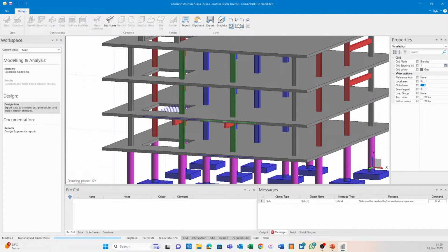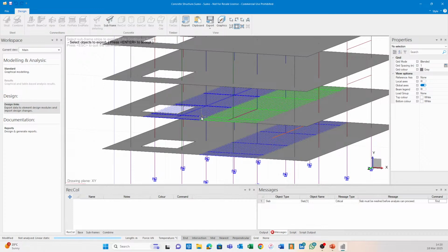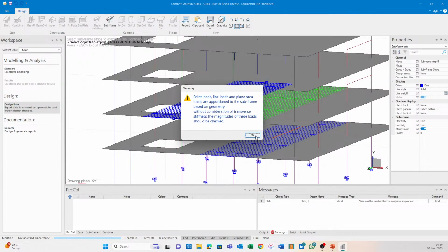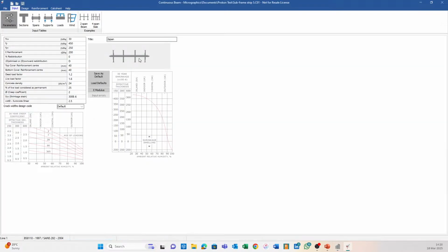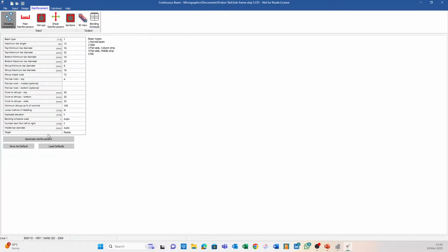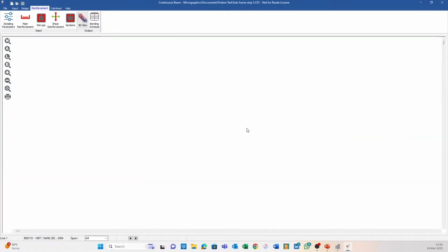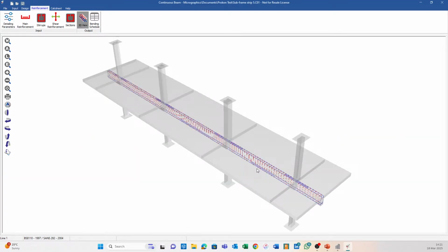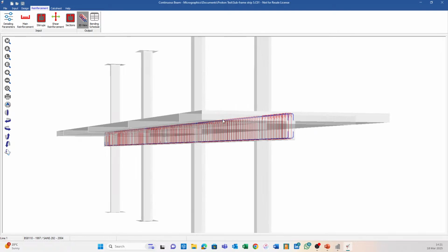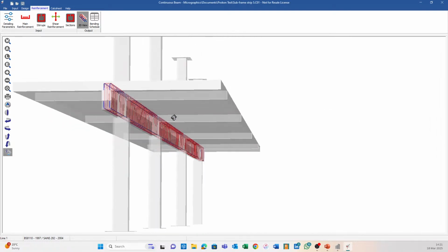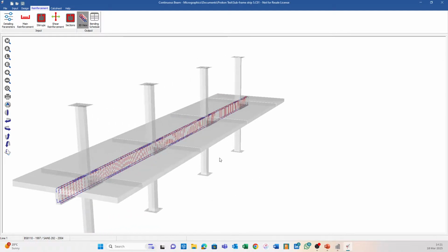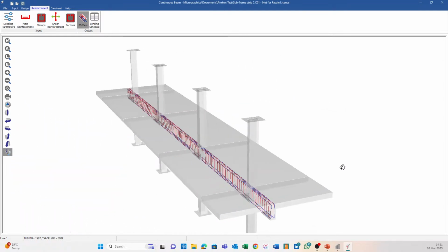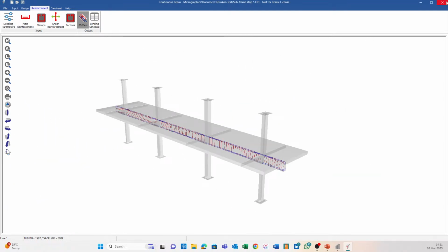So now if we take this subframe strip, we'll see a different story. And then you can see that beam is running straight through. If we go to reinforcement, generate reinforcement, and 3D view, we can see here, this is exactly what we want. There's that beam running straight through. All right, so it's not negligible. It is something important to keep in mind.